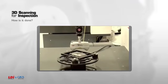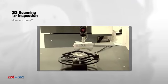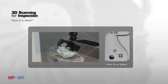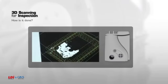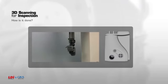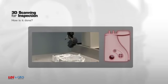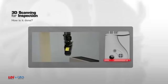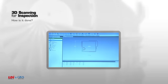A user can see exactly where he may need to get additional points, and the output is what's known as the point cloud, which is an accurate 3D representation of the part. The point cloud is superimposed on top of the CAD model, either using algorithms, which do a best fit, or using datums and features which reflect the design intent. Each point is given a distance from the CAD model and is assigned a color.